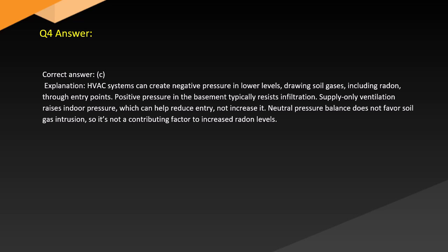Positive pressure in the basement typically resists infiltration. Supply-only ventilation raises indoor pressure, which can help reduce entry, not increase it. Neutral pressure balance does not favor soil gas intrusion, so it's not a contributing factor to increased radon levels.